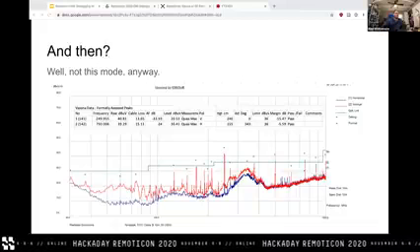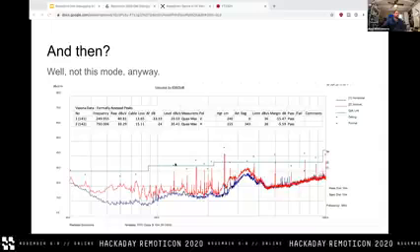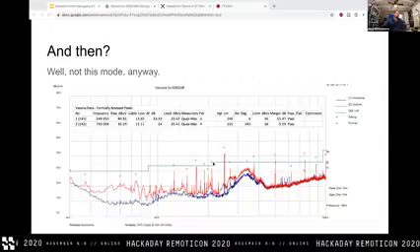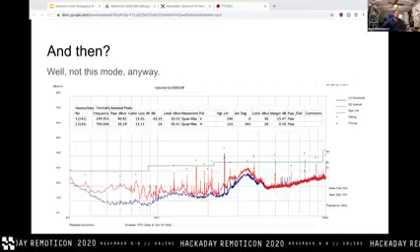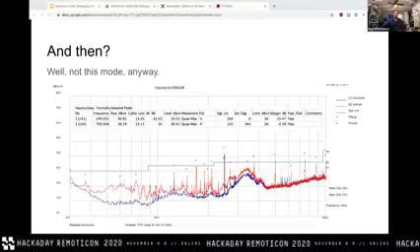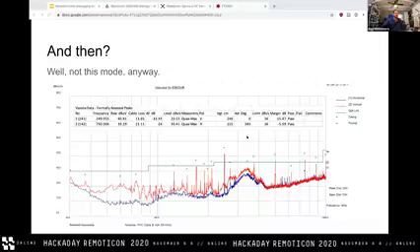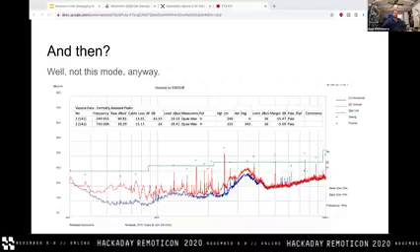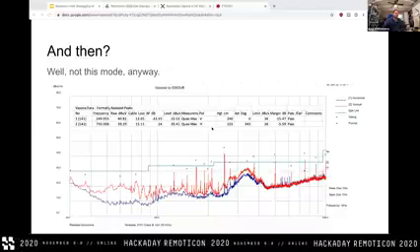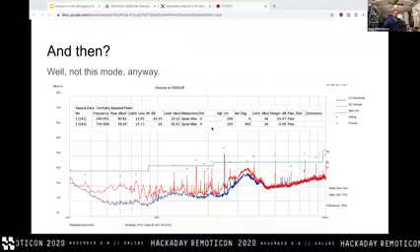This is yet another test mode of that same device where there are clearly a bunch of debug frequencies, and clearly a peak that, at least in the vertical antenna orientation, violates the limit line. But in that quasi-max analysis mode that actually matters for passing or failing a test, this product actually passes.